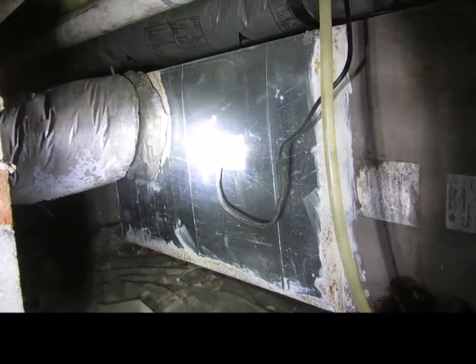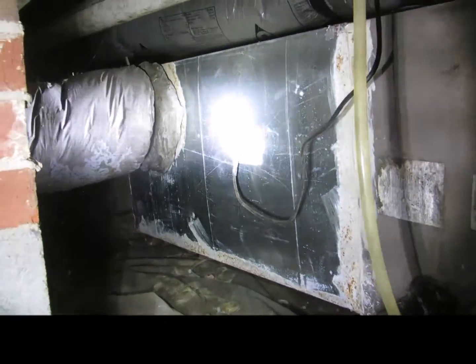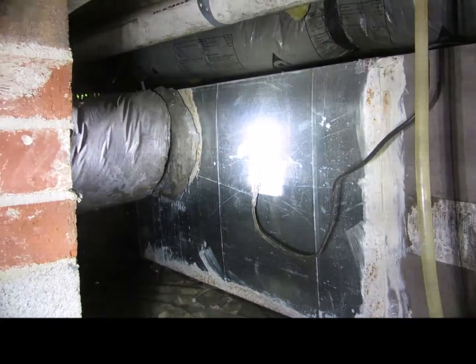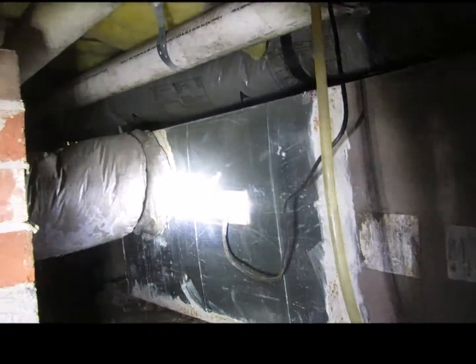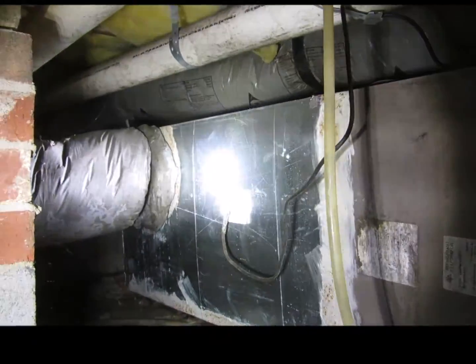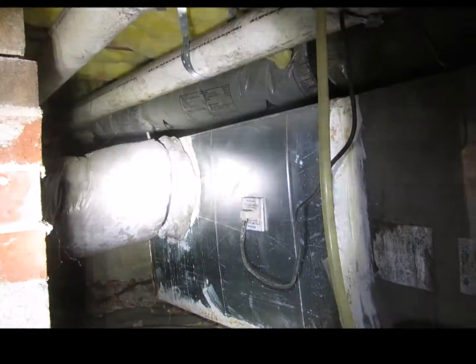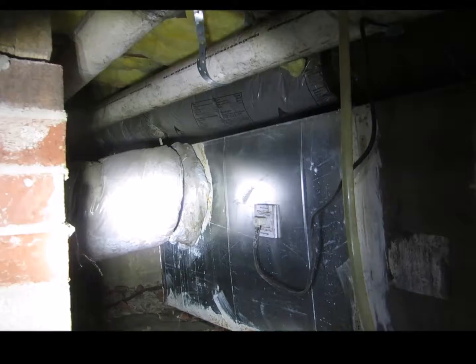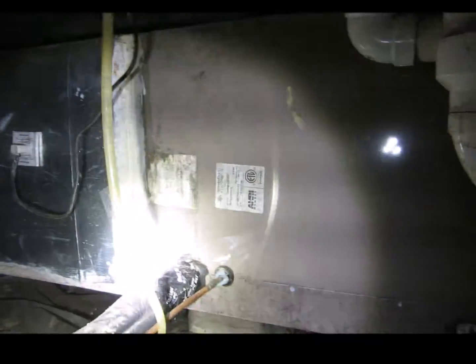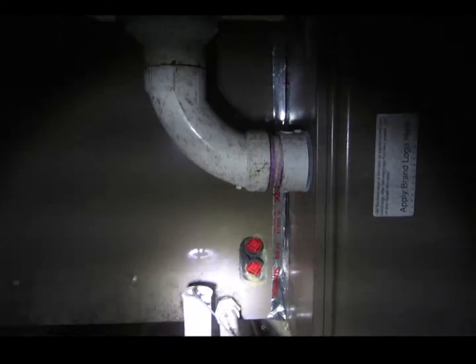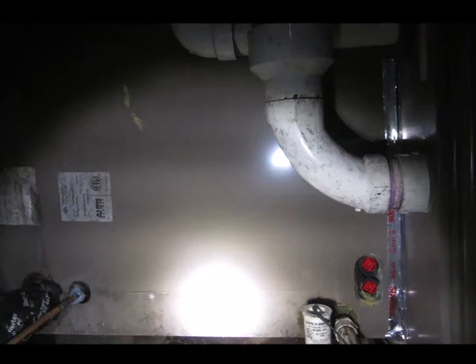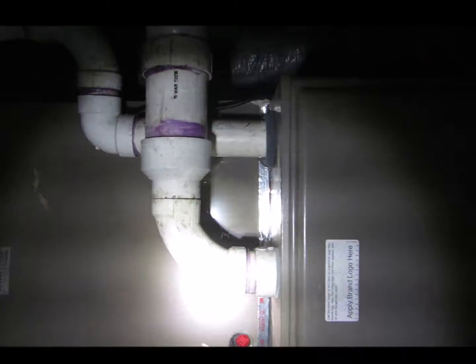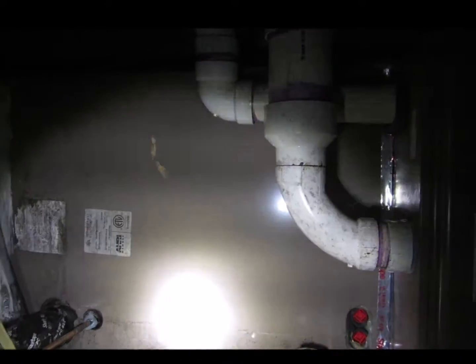We opened up this supply side distribution box, and apparently this microbe swifter, I think that's a UV light, and it's not working. Inside this box is a tremendous amount of mold growth. Also, it's on this duct coming off. It's a little elaborate to get into this system to check the coil, so I'm not going to do that now, but apparently this system is putting out way too much moisture, either the air handler previous, or this air handler.